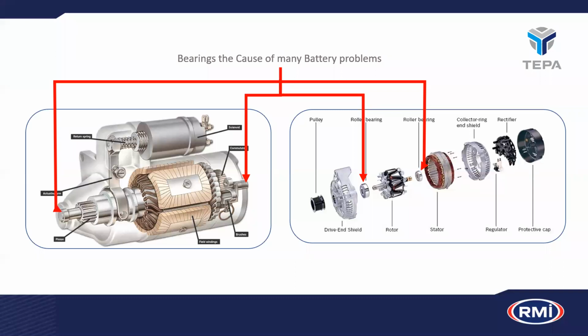And what happens when the bearings wear or even fail is that the armature will pull skew, and it ends up grinding against itself internally in the starter. So it'll give a half a turn and then it'll pull against the field windings in the starter motor, and that'll lock it up.